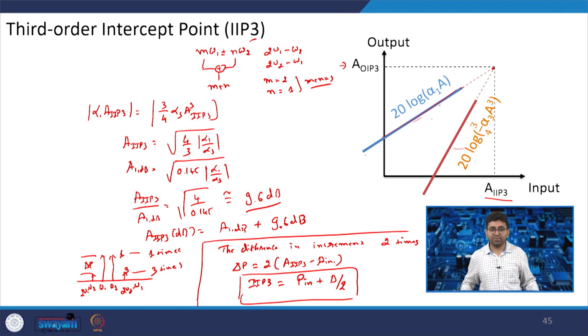You can also find the IIP3 by using a spectrum analyzer, and you can also find it by plotting a few points of the third order and first order points, then plotting asymptotically, and wherever they intercept, that point is the intercept point. We will discuss IP3 in more detail further. We will take one example to get more idea about IP3 in the next class. Thank you.